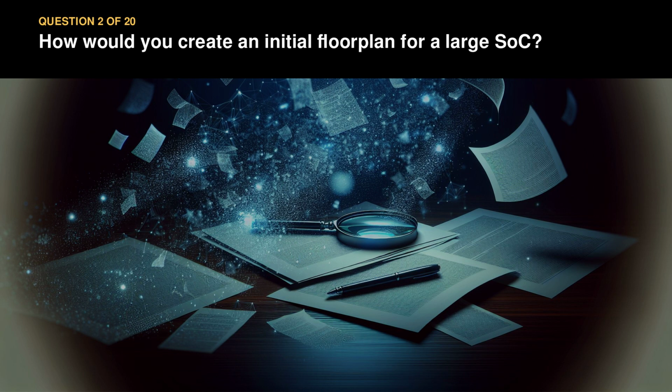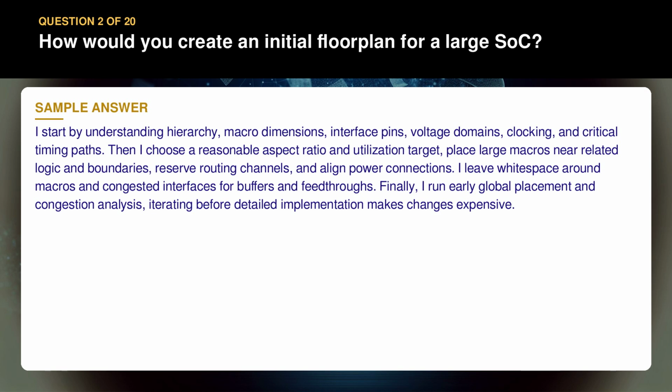Question 2. How would you create an initial floor plan for a large SoC? I start by understanding hierarchy, macro dimensions, interface pins, voltage domains, clocking, and critical timing paths. Then I choose a reasonable aspect ratio and utilization target, place large macros near related logic and boundaries, reserve routing channels, and align power connections.